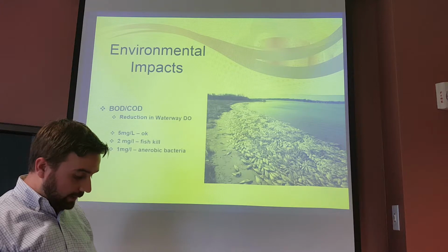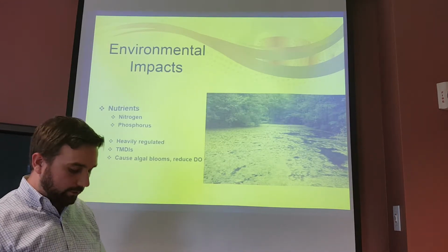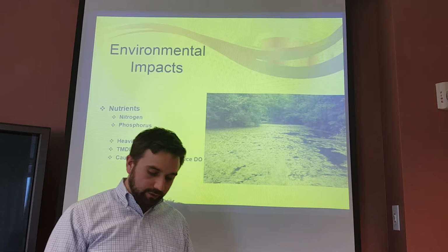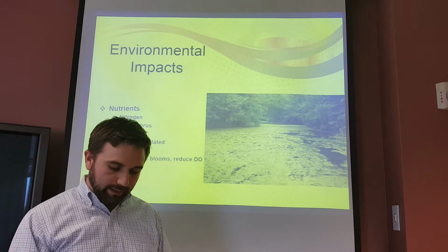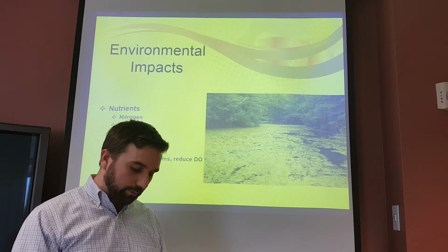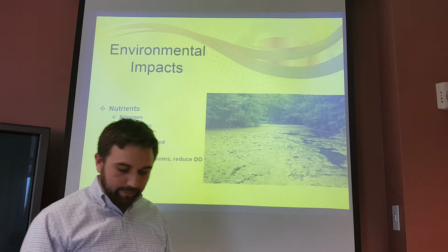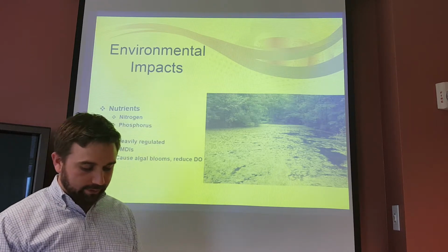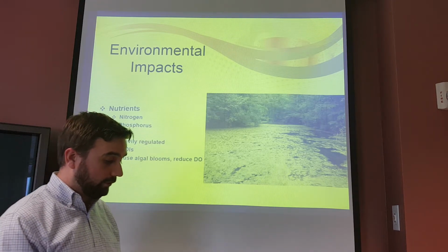Nutrients are another concern. Many treatment plants or industrial discharges have limits on the amount of phosphorus and nitrogen that they can send to a waterway. These nutrient loads can cause harmful algal blooms, which result in the reduction of DO. Many treatment plants have a strict discharge limit, which they pass upstream to some of their industrial users.